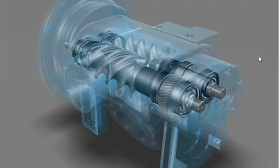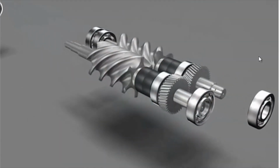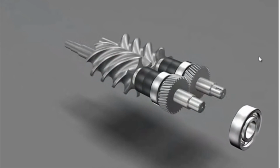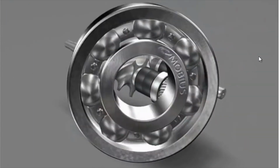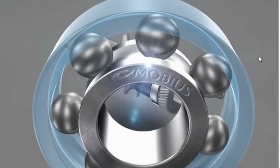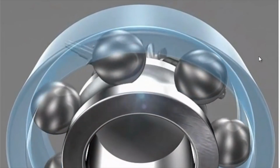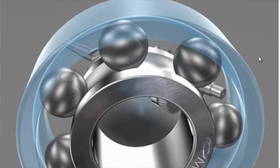We see here the internal components of the pump, and in particular we have the bearings, and in this case we have 7 steel balls. So if F0 is the frequency corresponding to rotation of the bearings, we may expect harmonics at 7 times F0. But the bearings are not the only ones.